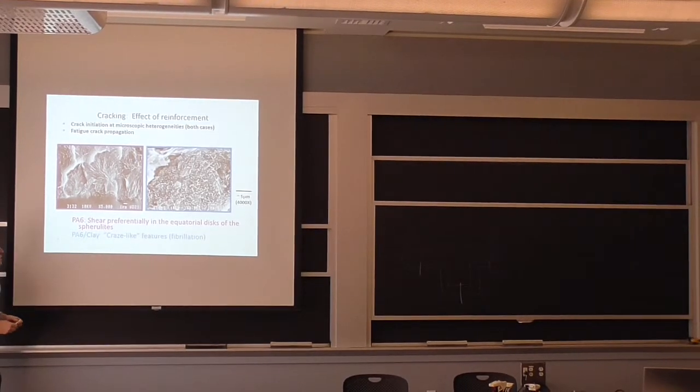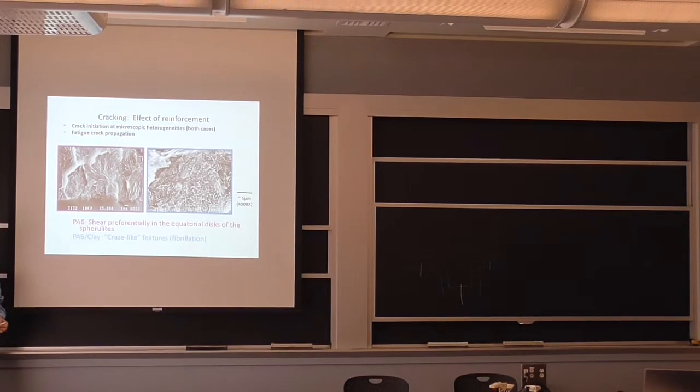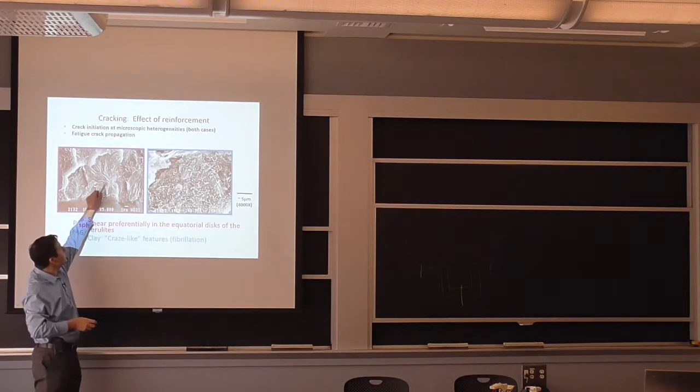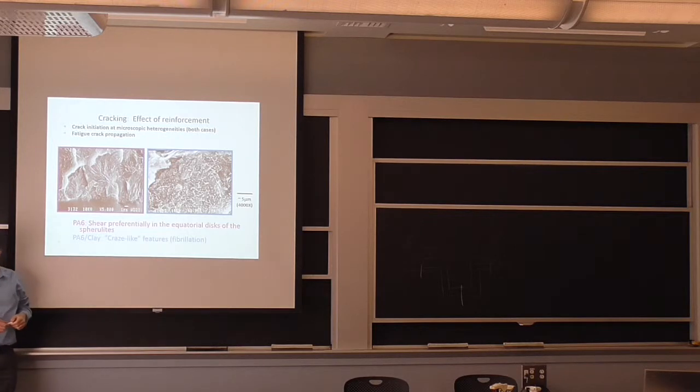You can see them individually. They are of the order of about 10, 15 micrometers, a little bit like what we had for the metals. One special thing on this one, right in the center, there's a little particle. That particle was a catalyst, which is how the crystallization started in that polymer.